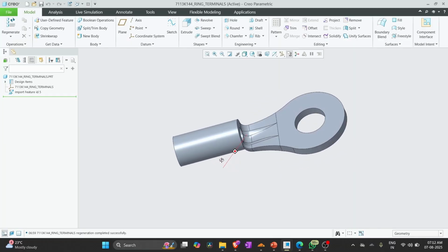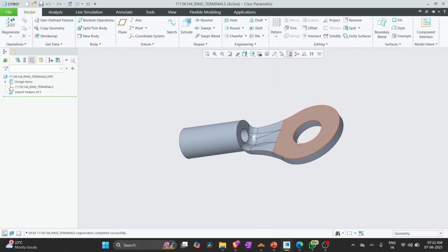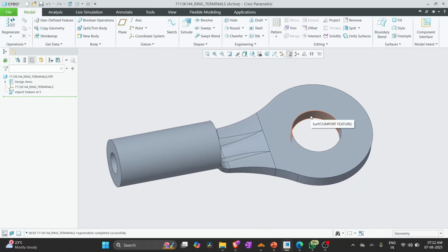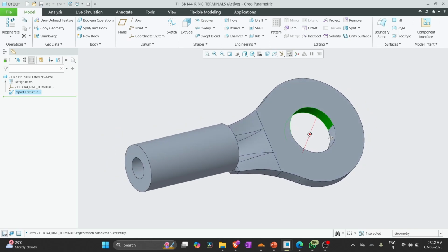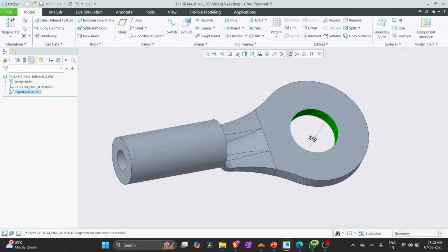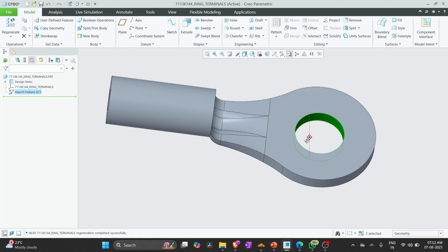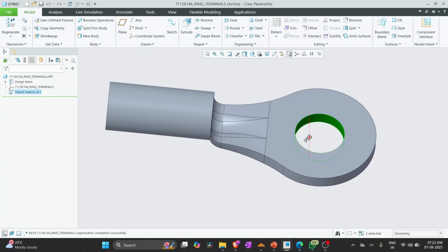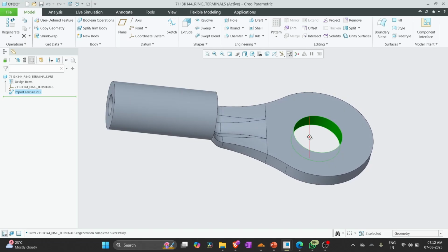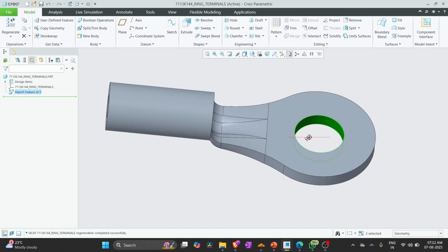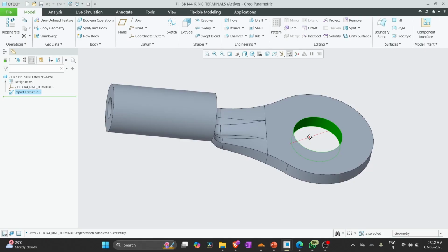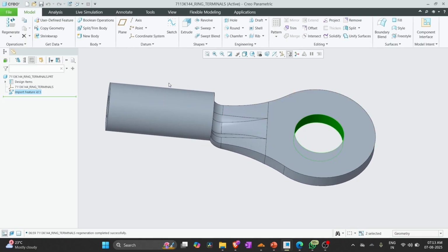So this is a 3D model of a lug, and this area is the mounting part of the lug. This is where the lug is to be placed, and the diameter of this lug is very important during design. So if we have an M5 stud or an M5 screw onto which we need to place a lug, then we need a similar M5 or a little bit higher size diameter of the lug.